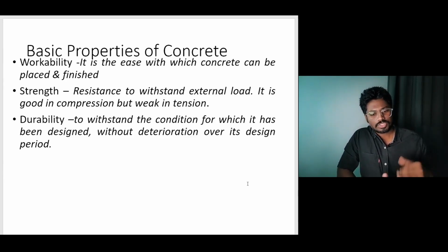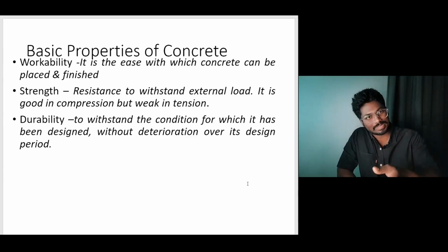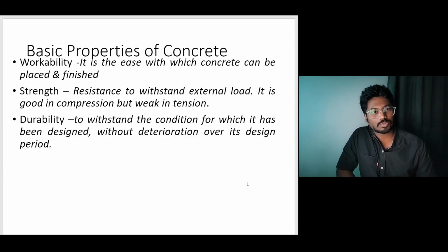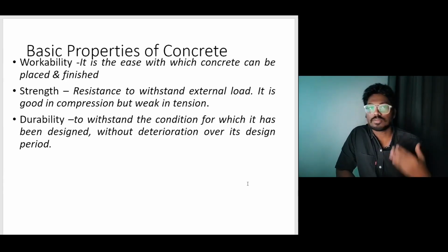Once you make concrete, that is nothing but mixing sand, stone, cement, and water together, the ease with which you mix all the ingredients, place it on your site, and finish it is called workability. The easier the placement and the finishing is, the more workable the cement concrete mix is.